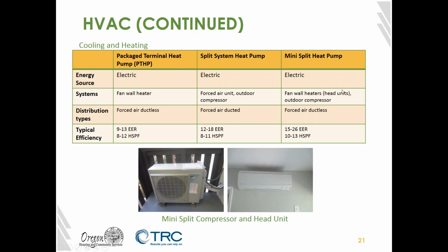And then a mini split heat pump also has an outdoor compressor, but on the interior of the building, it just has these head units. You can have multiple head units connected to each compressor, but they'll have a fan inside, and each one will blow heated or cooled air from that head unit. So there's no ductwork, just those head units.